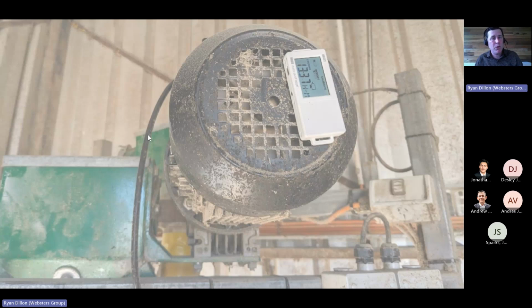So if you have a rapid door or a motorized door, we can install a motor runtime counter. And this actually just measures the hours and minutes over, say, a month that the door actually was open. So you have not only the number of door openings, but the length per door opening. You can also use light sensors, and we have light sensors that we use where the door opening triggers the light switch, the lights turn on. We measure the light because that's a little bit more reliable than trying to create a mechanical switch on the door to show it's open, because sometimes it might not be as accurate just based on our field experience.